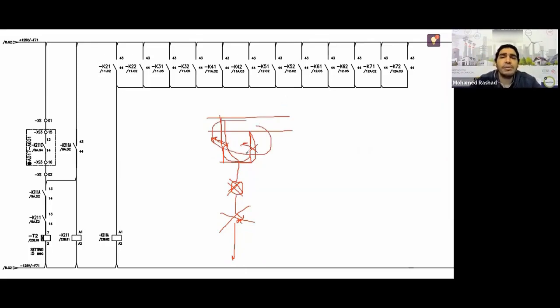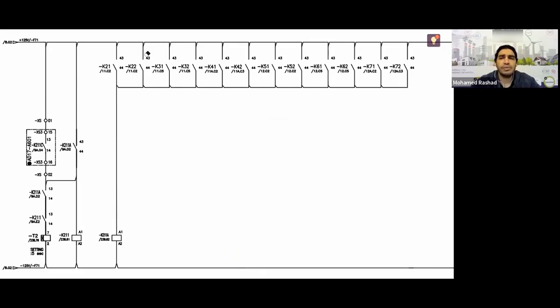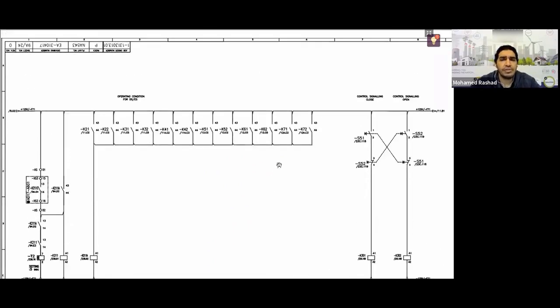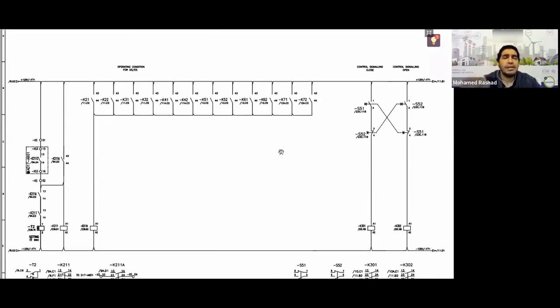All right, let's say now you have the same situation with any other cells. So what did the West come up with regarding double operation? Simply put, they suggested implementing a rule to relieve us all from this issue. It means quite simply that as long as I am operating a certain piece of equipment, I should wait for it to finish its operation. This is so that, God forbid, if there is any voltage or any problem with the SF6 gas or anything else, it's resolved. Just stay with me first in this equipment, isolate it, and you can work on another equipment.